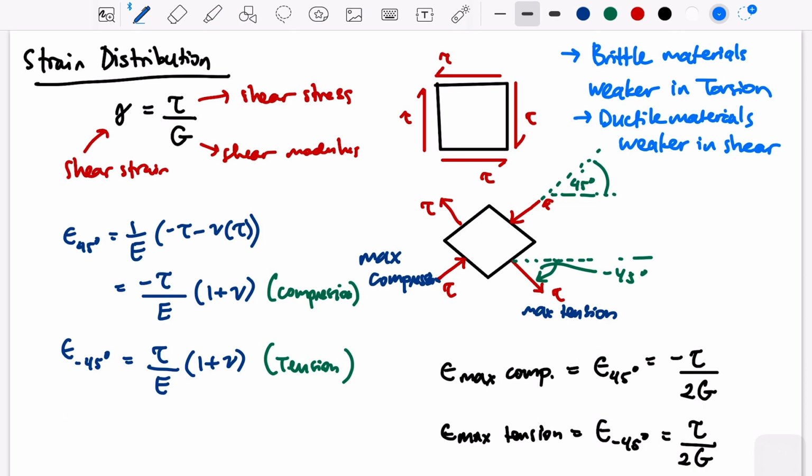If you have ever seen torsion testing for, let's say, steel, if you imagine steel and you give it torsion, you will see that it will twist, and later when it fails, when it's broken, you will see that it makes a 90 degree break.